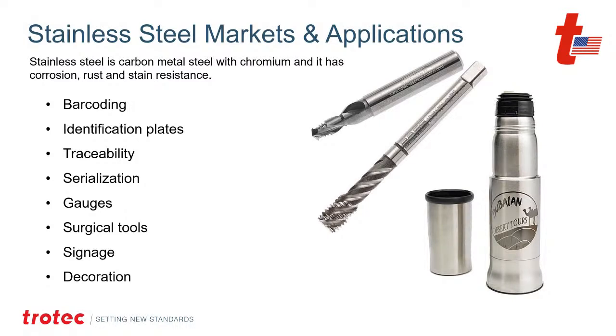Basically, the laser gives you the ability to put a permanent, durable, high-quality mark onto the surface of your product, your application, in this case. And instead of adding an additive like a paint or another process or an inkjet, it is far more durable. Especially when it comes to tooling or barcoding or serialization, where you cannot have that image or graphic be removed easily, it's going to allow for more traceability for long-term wear, also being able to trace within time. And that's where the laser comes in and why it is such an advantageous technology for processing materials like stainless steel.